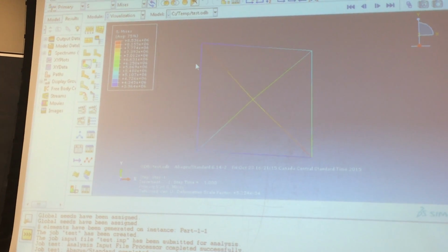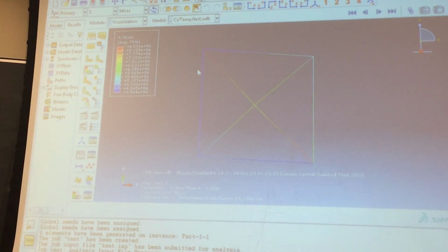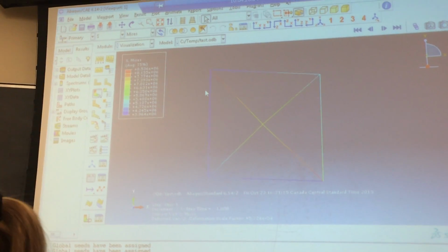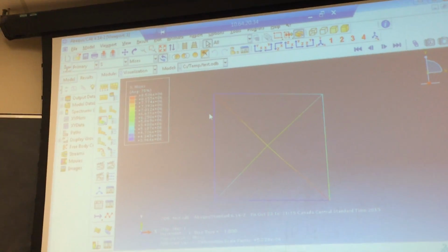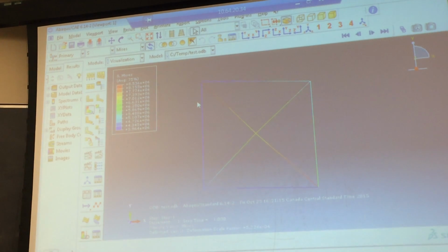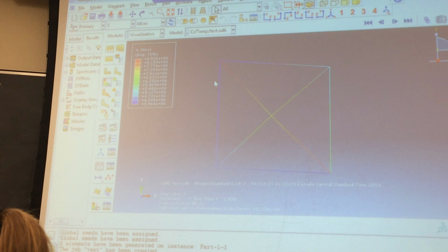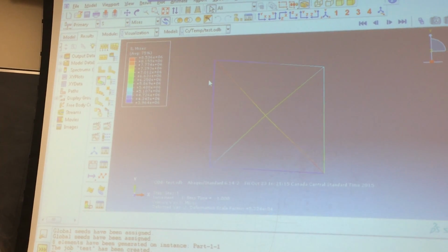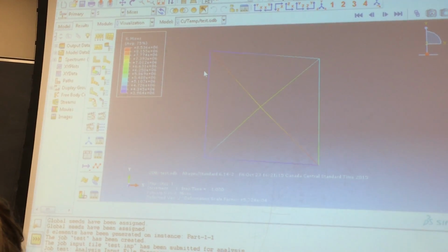In order to verify your model, you have different options. Like I said, the first option is hand calculation. Not for large models, but if you do a simple procedure for a smaller model, you can check it out and make sure it's correct. The other system, which is a bit more complicated, is to treat your model as a cantilever beam and put two different sets of loading.